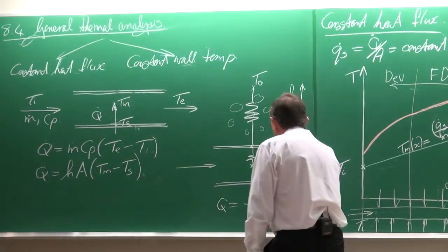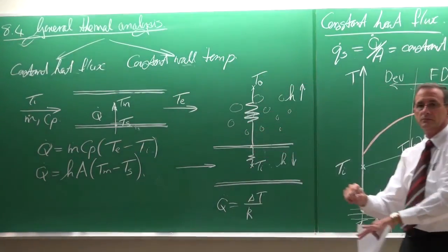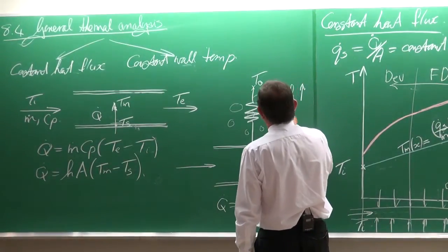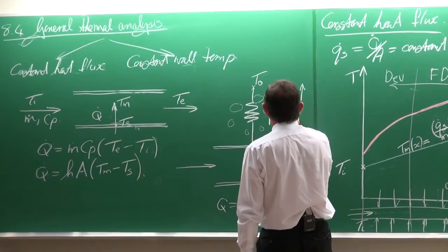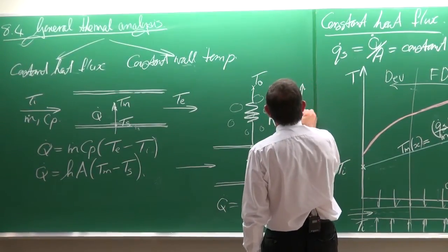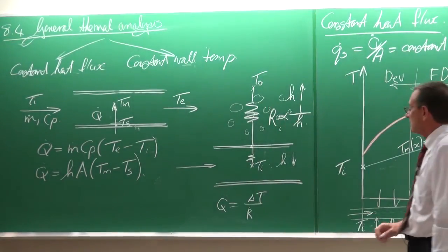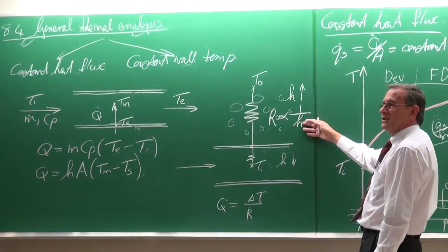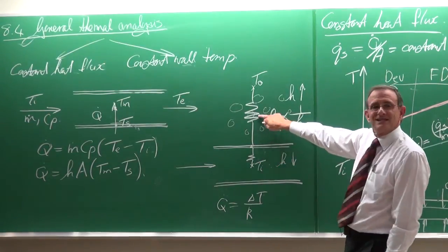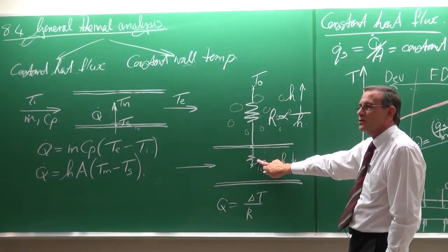And we are talking of the resistance of this term plus that term plus that term. Okay. Now the resistance on this side, or for any convection type of problem, is directly proportional to 1 divided by the heat transfer coefficient. Okay. So if you look at this resistance in comparison with this resistance, you will see that this resistance is negligible. Okay, in comparison with this one.